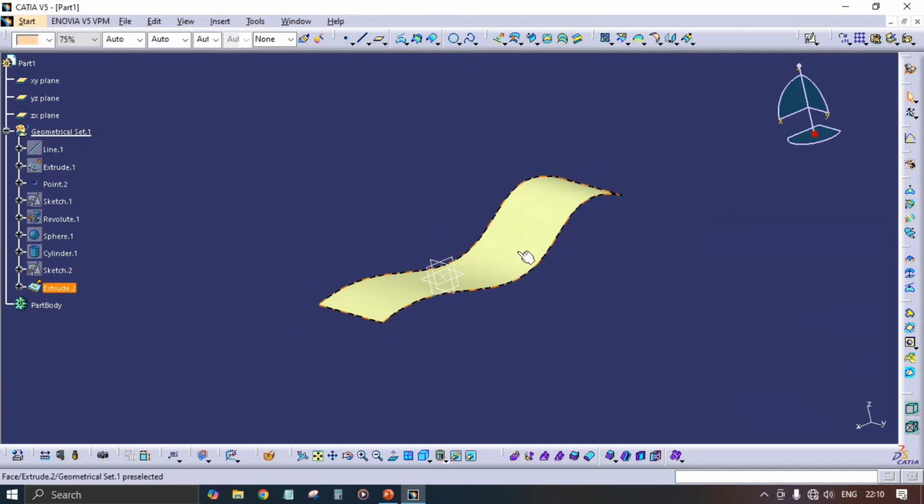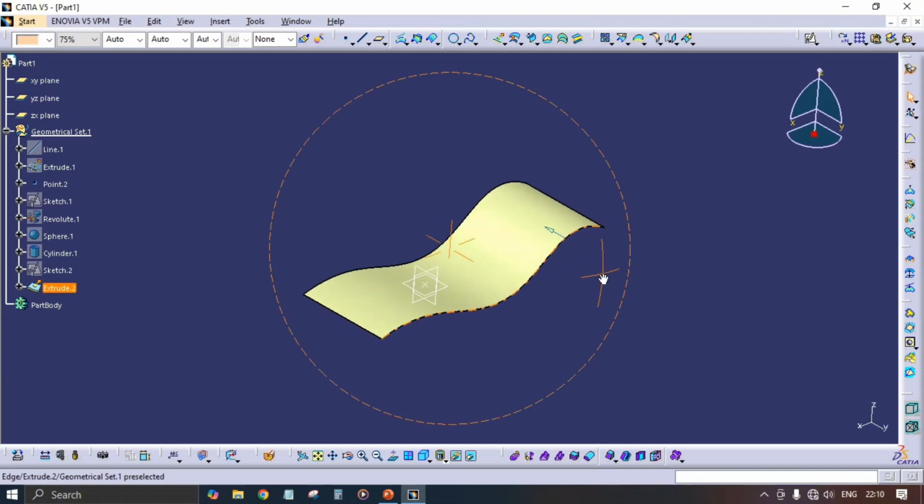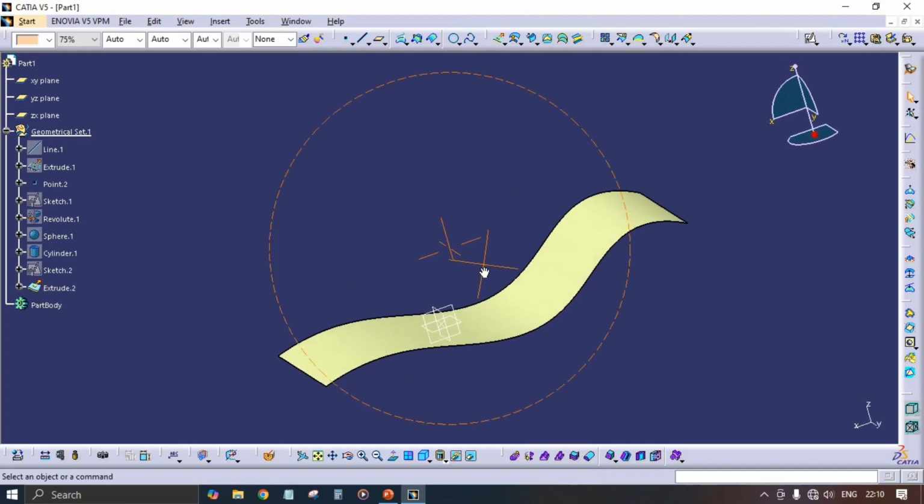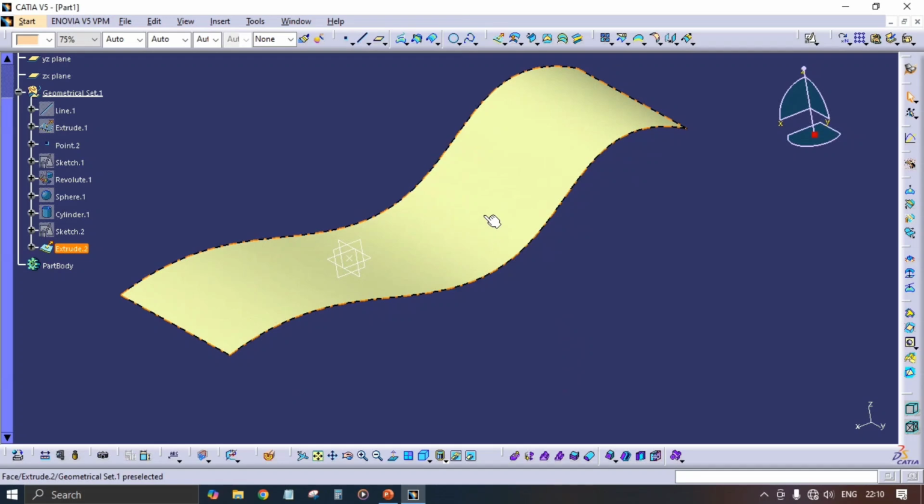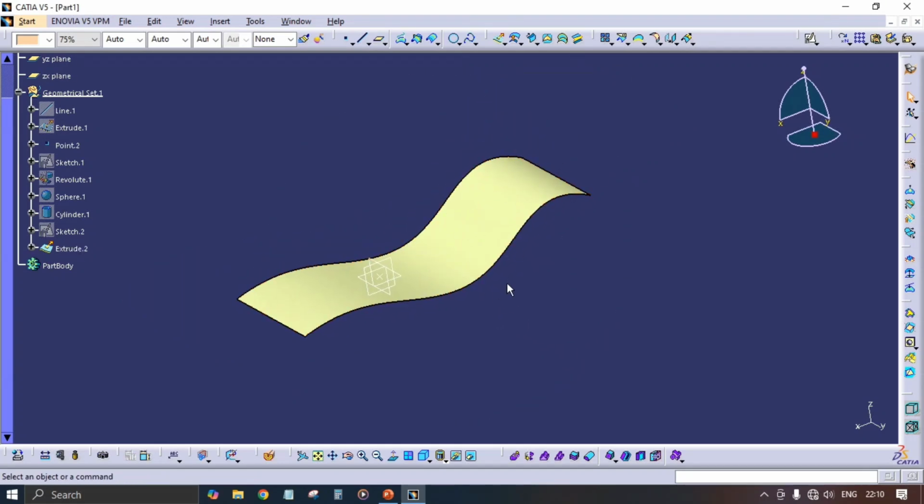Okay, and this is how the extrude tool will also work. Now I want one more surface at a particular distance, an exact copy of this profile, and that may not be possible, right? Because I used the spline command. Making and matching two different splines takes lots of time. So I cannot make one more sketch and follow the process like that.